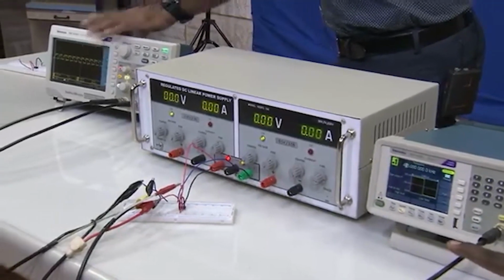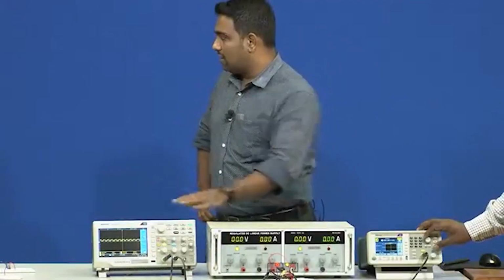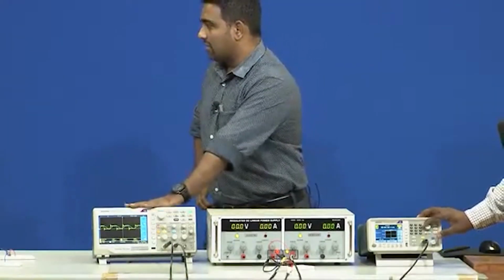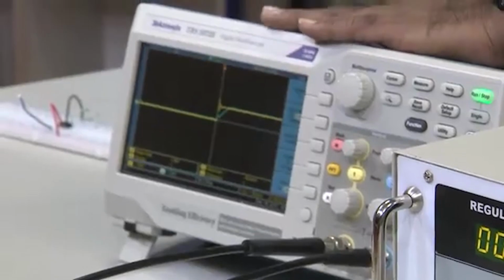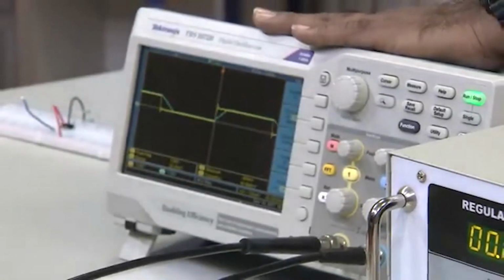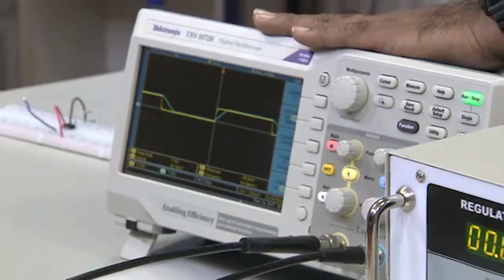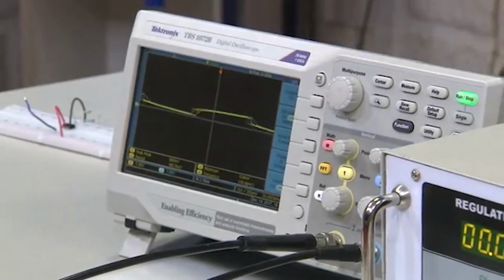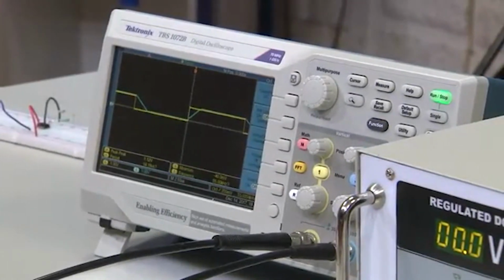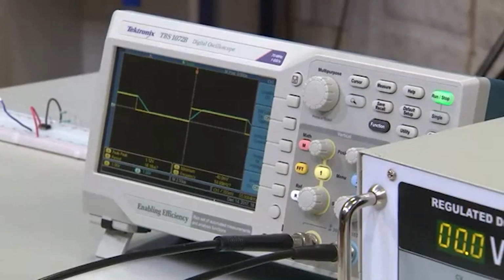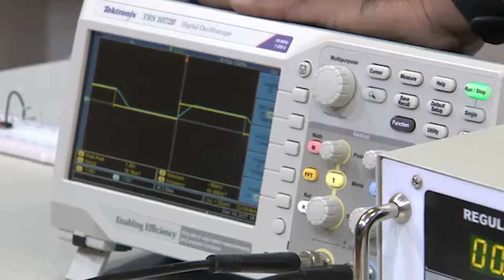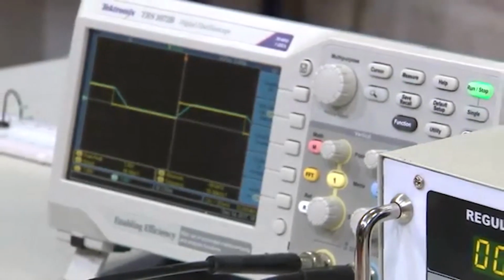But if he goes on decreasing the frequency, can you decrease it again? Yeah. If you see, as he is decreasing the frequency, the distortion becomes less, and it is easy to understand or easy to measure this slew rate. So, this is how we can understand. From that we also understand that at a particular frequency the op-amp cannot be operated, that is, there is a maximum frequency at which the operational amplifier can be operated. So, there is an easier way to understand at what frequency the operational amplifier can be operated. At that frequency, the slew rate will be distorted.